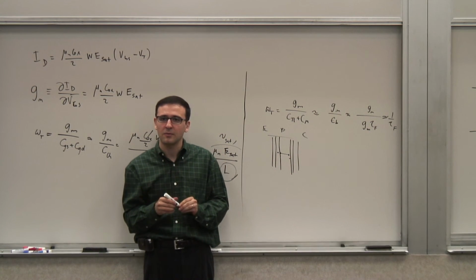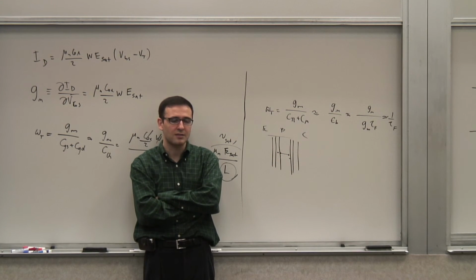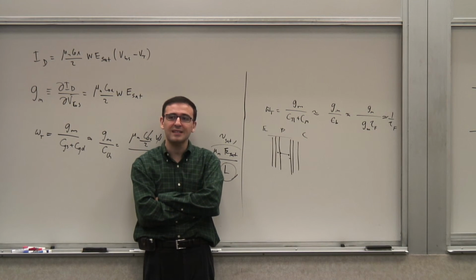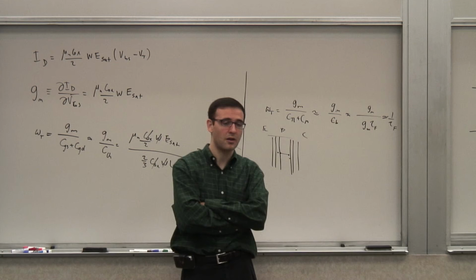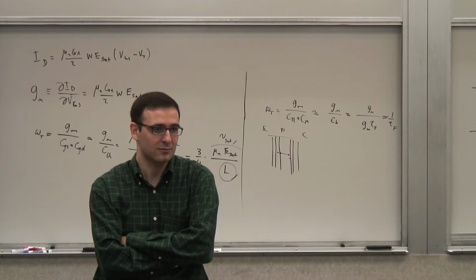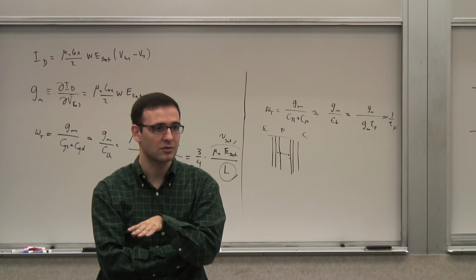What is the mechanism for an electron going from this side to that side? It's diffusion, right? It's random thermal movement. Now, we know that electrons move extremely fast thermally. You're basically taking advantage of that really high speed movement of electrons. And the reason they move really fast is that they're very light. So for a given number of kTs, I guess 3 halves, they move really fast at any given temperature.